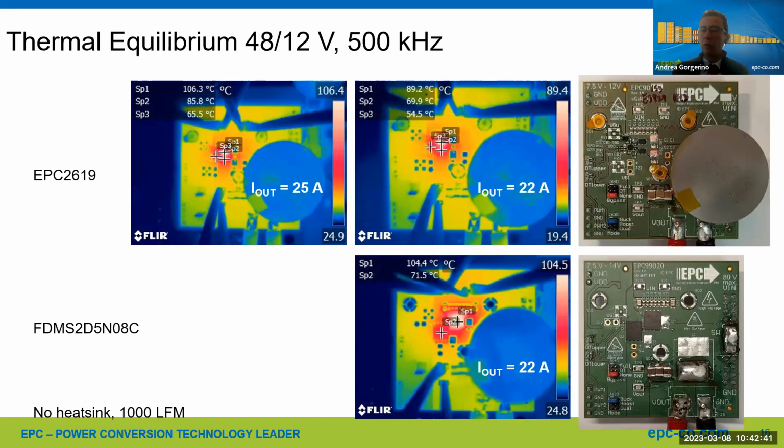You've got to make those 2 loops at 90 degrees and minimize the common source inductance. And when I mean 90 degrees, it means to be really next to it. It can't be up here or down there, because then it's not 90 degrees anymore. It's 45, right? So that's the first one.